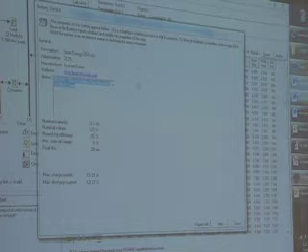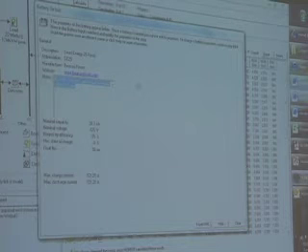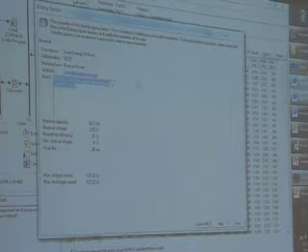Well, no, that's the round trip efficiency, because the parasitic load is there even if no energy is going in and out, right? So the round trip efficiency is how much of the energy that went in can you get out? You could think of it as two different kinds of losses. One's a function of time, and one's a function of throughput. And we should have a parasitic load in there, but we don't. So we should add it.